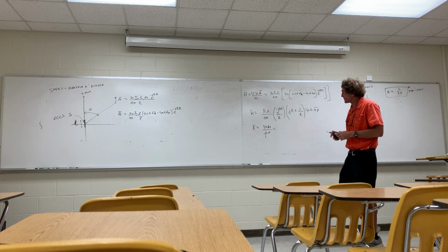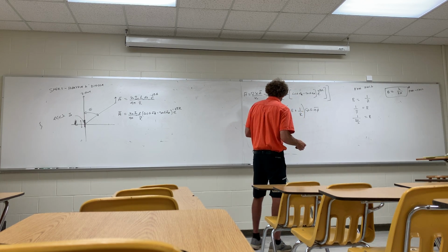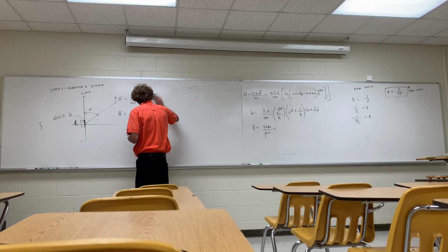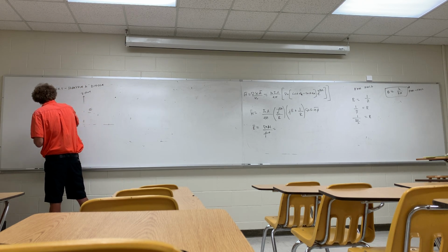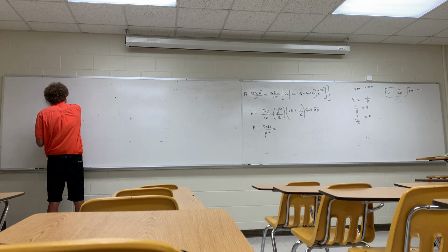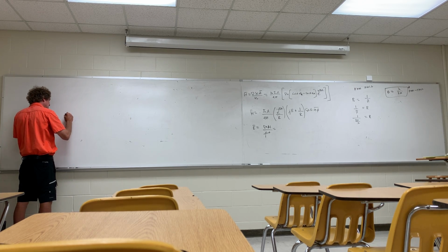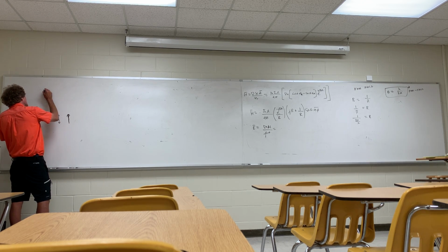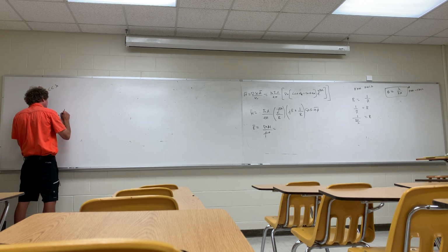Now when you're in the far field, a couple things happen. And now I'm going to tell you what happens in the far field. I'll get to that in a second. And this is really the important part. So now, when you have your short dipole antenna vertically oriented, and it's got a length L, and L is much less than lambda, has a current I naught on it, constant current, by the way.